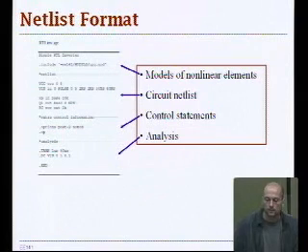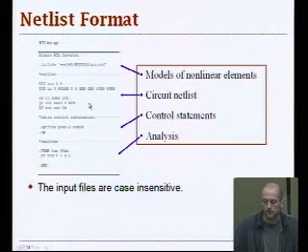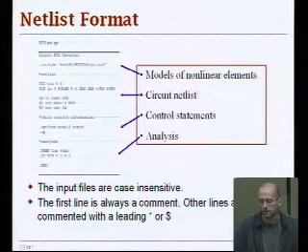And then you have some control statements. You have this to be able to save your simulation results. And then you also specify what kind of analysis you want to perform. You can do transient, operating point, DC. And in this homework, you will need to do only transient and DC analysis, and it always ends with this .end statement. So it's quite simple. You basically have to understand the structure. The input files are case sensitive. That's one thing to keep in mind, but you can read plenty of that in your documentation.